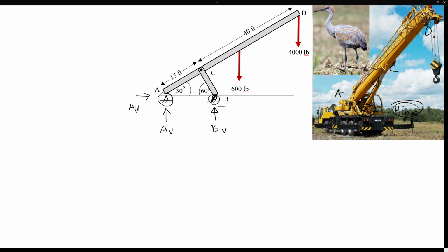So when you have a hinged connection, then you also have a horizontal component there too. So now you have four variables. You only have three equations. So you won't be able to solve just by simply applying the techniques we have discussed so far. So we'll have to apply the frame analysis techniques here. So let's show you this step-by-step process.